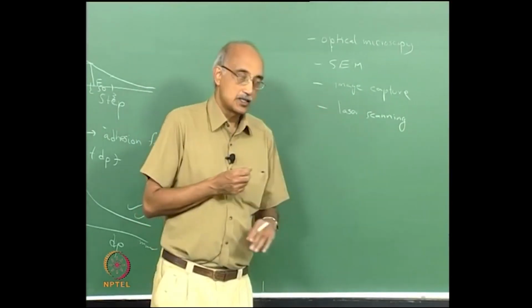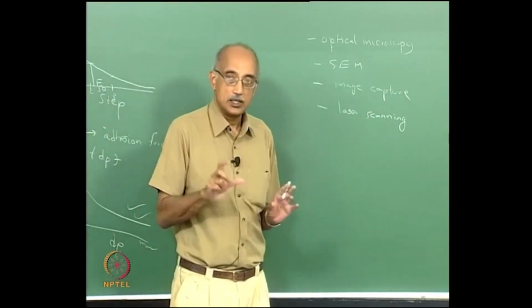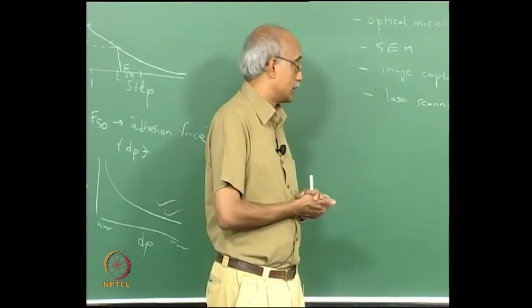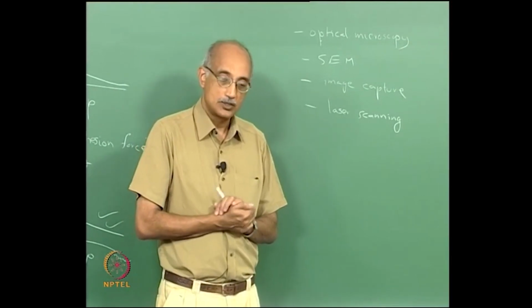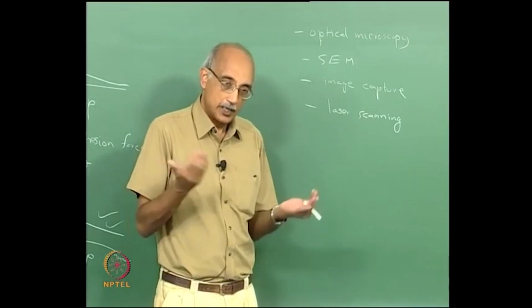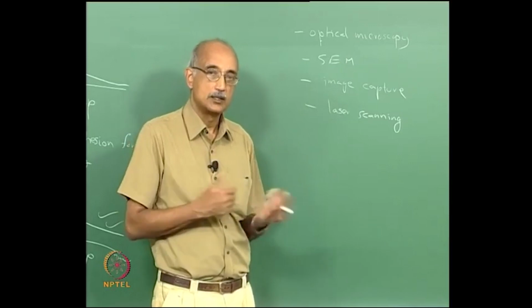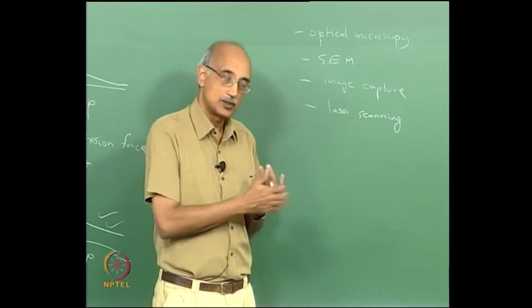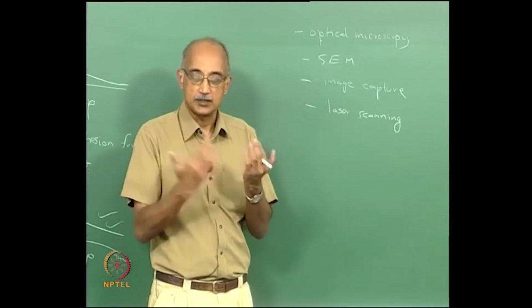Image capture and laser scanning we talked about earlier as two essentially alternative techniques to look at particles on a surface. Image capture works very well when you are trying to do this experiment on particle adhesion, because essentially you take a surface, you deposit particles on it, take a photo, and that is your reference. Then you apply a certain force to the surface, and after the force has been applied, take another image and then do an image comparison.